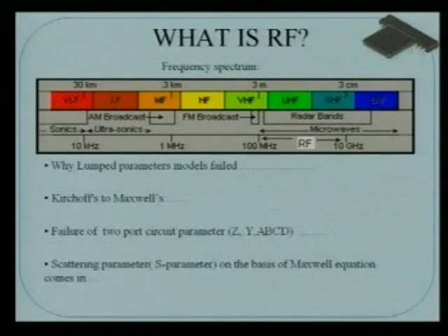So the first thing you have to know, very fundamentally, is whether our KCL and KVL are valid in RFIC design or not. Otherwise we have to really go into the Maxwell equations and solve all the electromagnetic equations for designing the RFIC. But thank God that world is not so complex, so under certain circumstances we can really use the standard KCL and KVL even for RFIC design. So what is the logic behind it? Let's go into that.